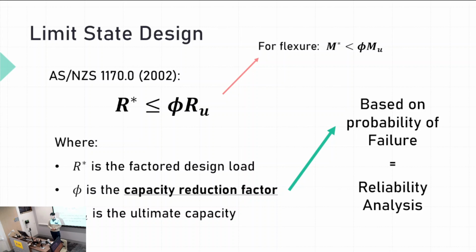This number comes from the consistency of the material and how often it fails. With steel, for example, in the design codes, we see numbers close to 0.9, 0.8. Concrete, we see 0.65, 0.85, these kinds of ranges.